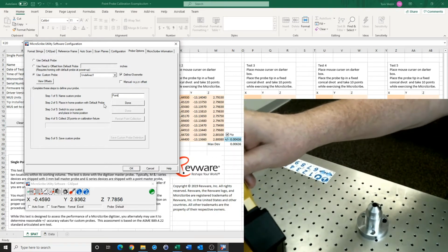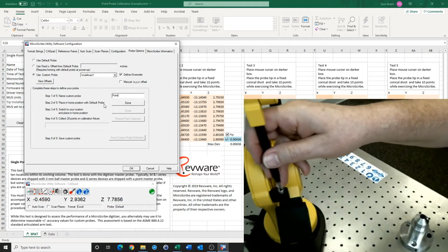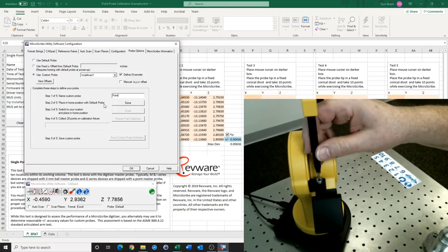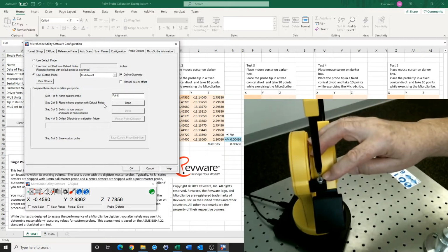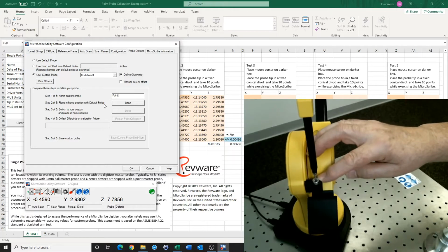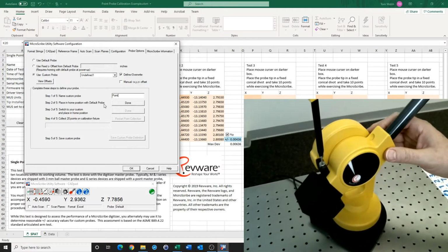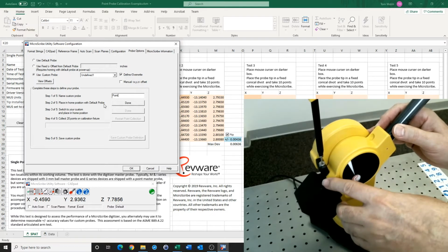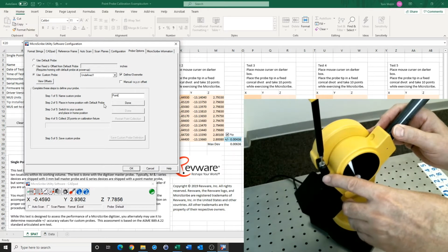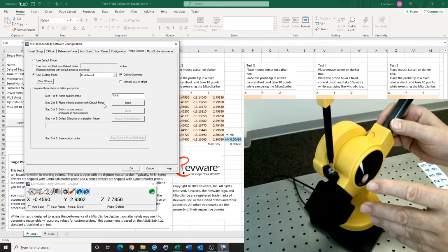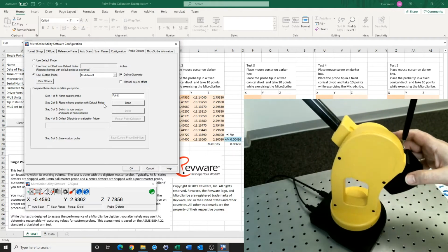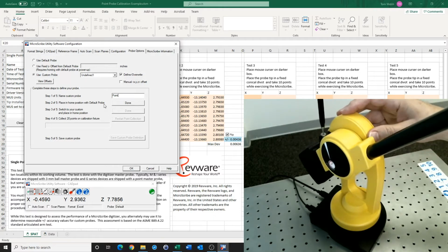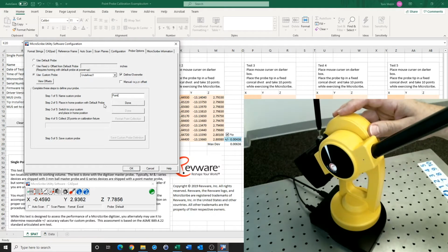Now, to get the MicroScribe into the home position, first of all, we're going to make sure that the ball seats really well down in the cup. We want to make sure there's no debris down in there that might be keeping it from seating properly. And you also want to make sure that the counterweight is solidly up against the base of the rest. So that's part of the home position. The final would be, for a MicroScribe I or a MicroScribe M, to turn it completely counterclockwise.